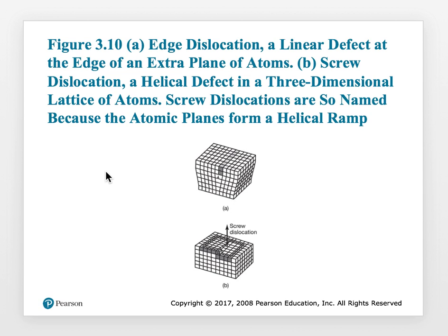Okay, so if you look at the stress strain curve, if you can see where the elastic modulus is, so if you go beyond that, then you are actually creating the movement of edge dislocations and screw dislocations. So please understand this only in terms of describing the process, but the actual engineering numbers comes from your stress strain curves for any given material.